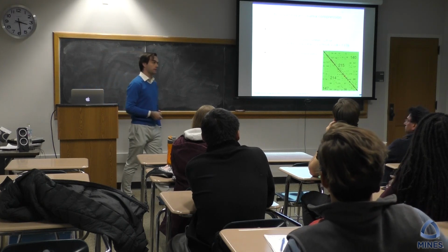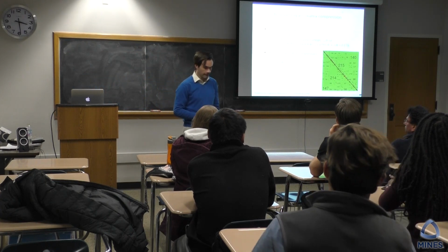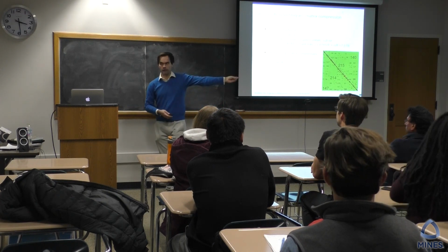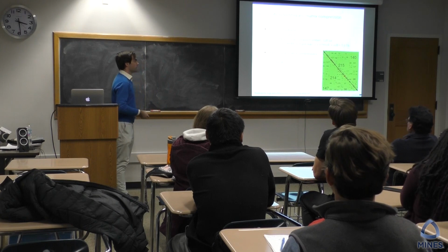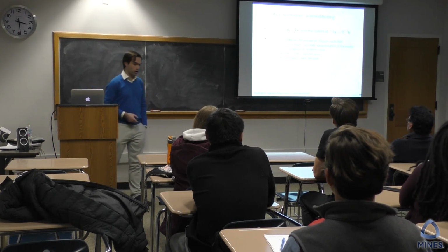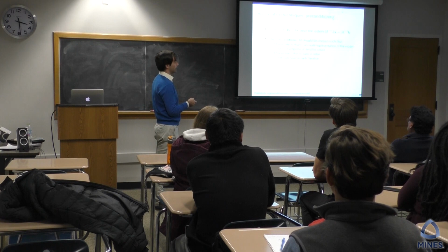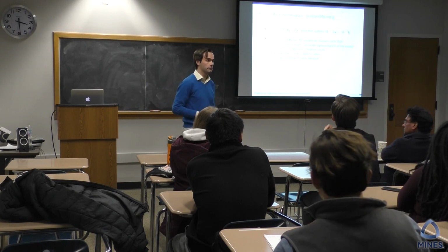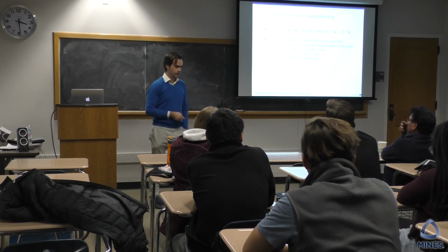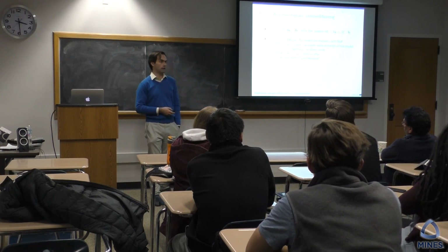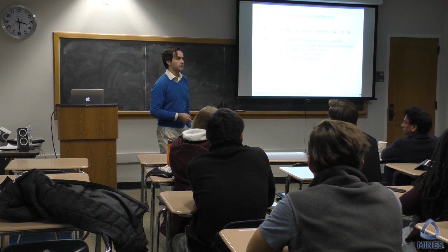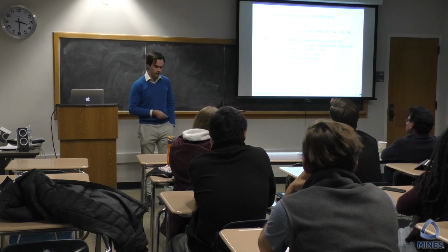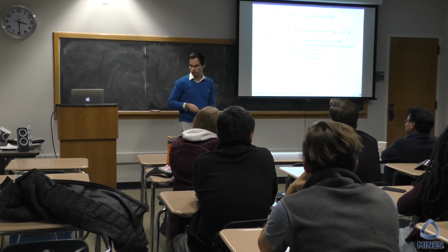So now we can store the matrix in our RAM. We can also do a matrix times vector multiplication with this compressed scheme. So now we can solve it. So yeah, the whole point, this is again similar to finite element methods. We need to solve Ax = b, where A is a matrix of 500,000 by 500,000. Of course, you can do a direct solve and LU factorization, but that's very expensive. So we use an iterative linear method, GMRES. So we iterate to the solution.